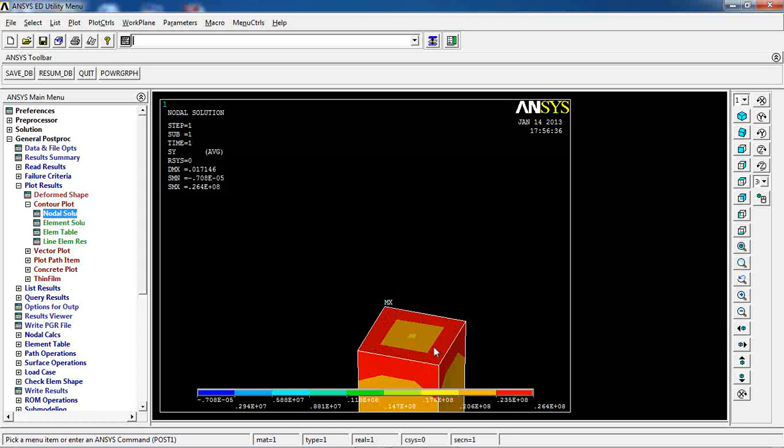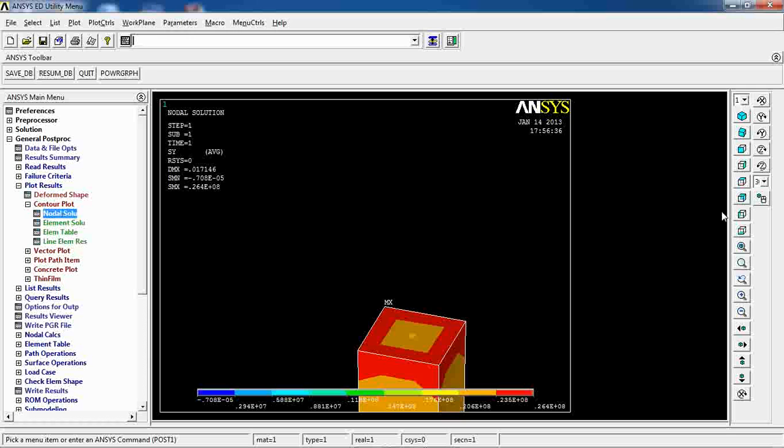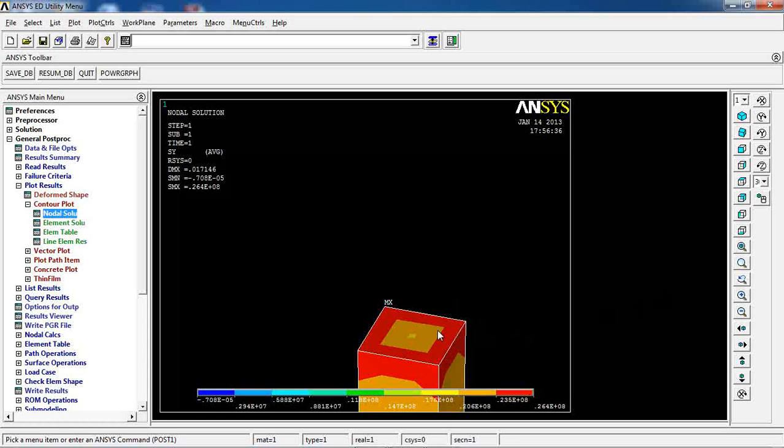And it's because as the material is expanding in its height direction, it's about to shrink in its cross section, so it's about to shrink in X and Z directions, and because of that it's facing some stresses in these two directions, and that's why we don't see a constant stress in here.